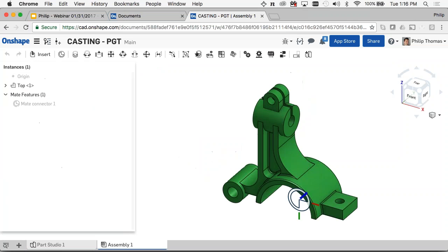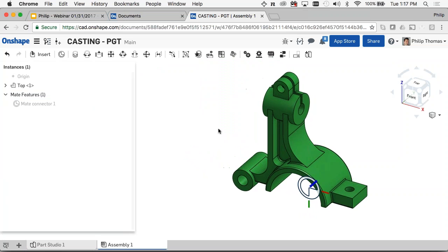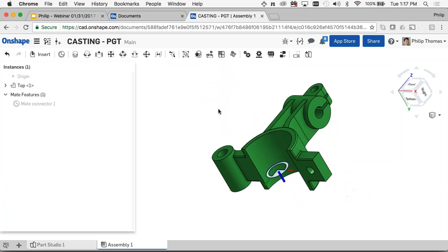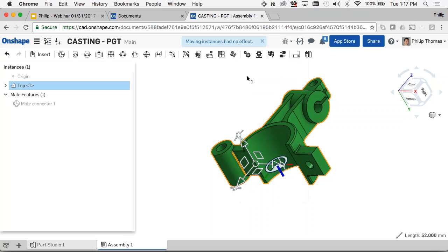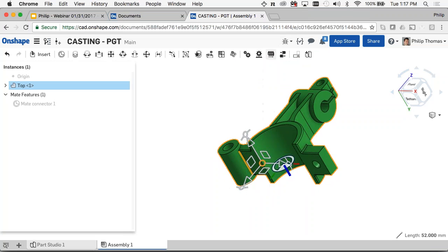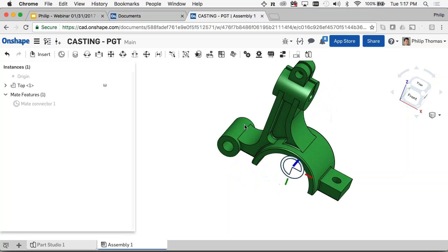All right, in the assembly, I'm going to go ahead and, it's already here, just pull this off. I could make this anywhere I want, but what's interesting, and I'll show you how to attach it to the origin. So if I said this part, move that to here, I can go ahead and say anti-align with Z, which orients the part with the Z-axis, and then I can say right mouse button, move to origin. Cool. Next thing I like to tell people to do is to fix that first part.